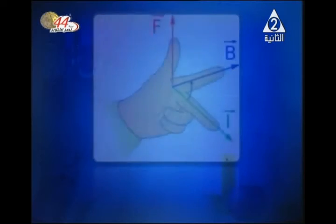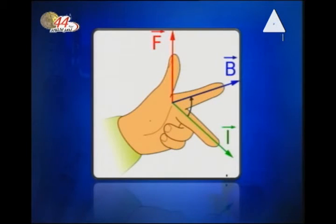So once again, the forefinger points in the direction of the field. The second finger points in the direction of the conventional current. The thumb automatically will give the direction of motion or direction of force. And never forget, we apply Fleming's left-hand rule when current causes motion.